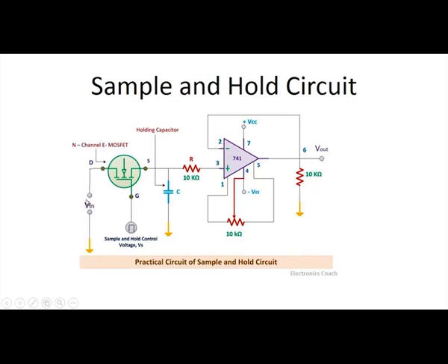If it is a small signal, then you can use an operational amplifier in voltage follower mode. Since the voltage follower has high input impedance, it will not act as a load to the small AC signal. So, you can use a voltage follower circuit in between the input signal and the MOSFET.